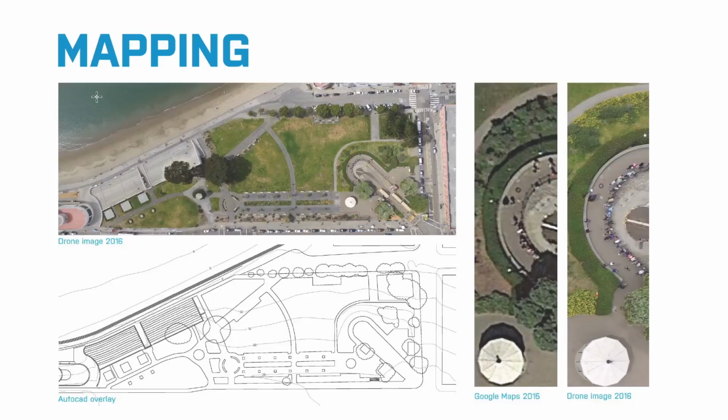So that was kind of the artistic side of how drones can be used in landscape architecture. Now I'm going to go into more of the scientific, more data-driven, practical uses. So here's a really crude way to make a map: take a series of photos looking straight down and then Photoshop them together. Then you can trace through in AutoCAD and create a really quick map of the site. So this would be useful for spaces where maybe Google Earth imagery isn't current or it's not of high enough quality where you can trace. The drone imagery is much higher resolution than standard Google Earth imagery.